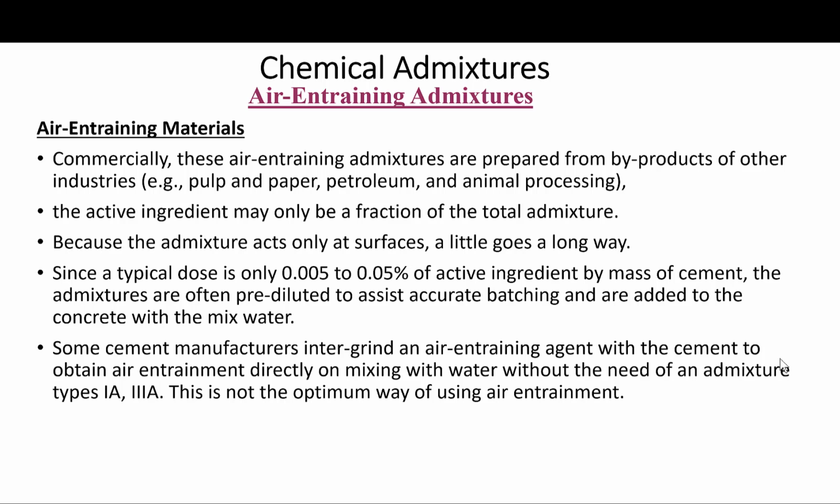The use of air-entrained cements may not actually give the desired results. Because of this limitation, the use of air-entrained cement is limited to small jobs, not large-scale jobs. So it's better to add it as an admixture to the mix.